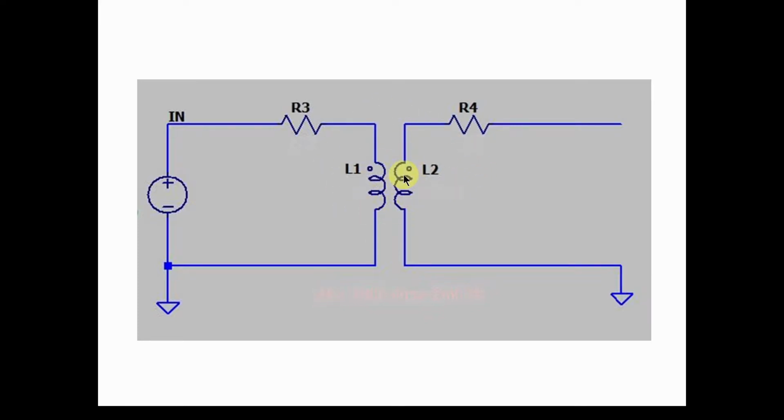So let's start adding some things that we have figured out so far to see where we are. Well, we know we've got 117 volts AC rating on the high voltage, 12 on the low, 4 amps on the 12 volt secondary, and 0.4 on the primary. So let's start looking at what kind of inductance we expect here, what kind of inductive reactance or impedance of this inductor, because we're going to have to figure out an inductance for this to model it.